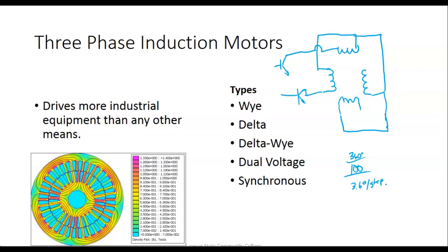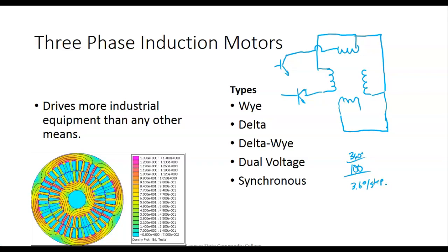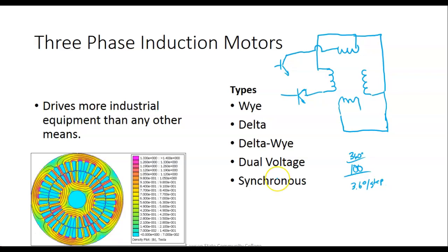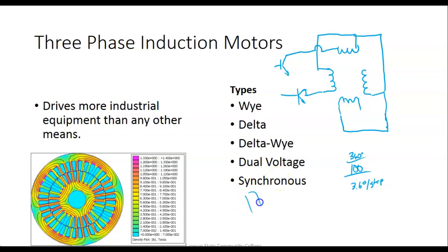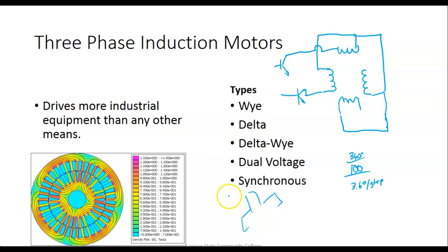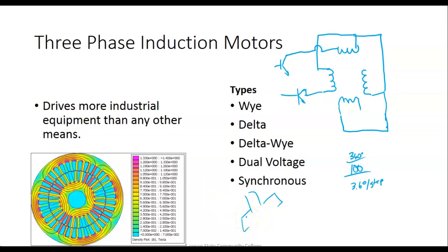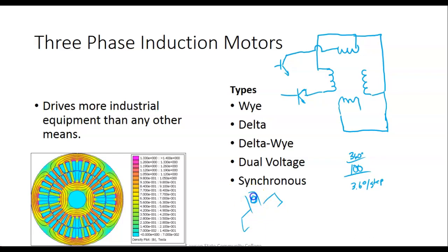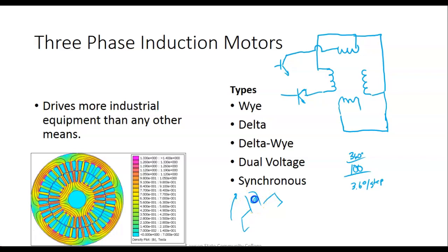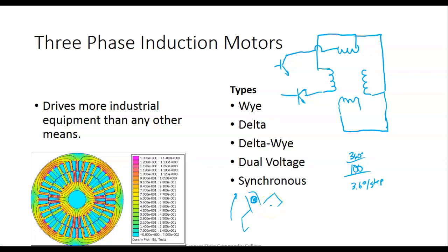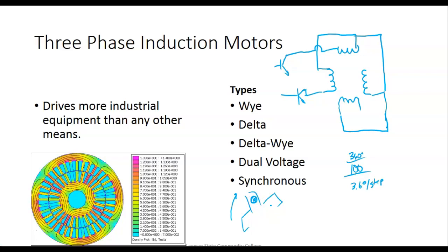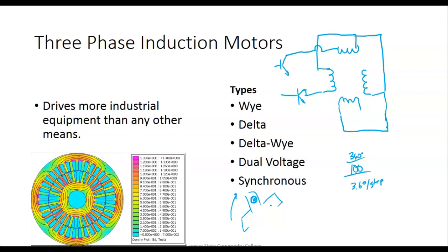Well, I started the carousel running, clicked it off, and got it out in the center. I turned it on, and what it does is it starts stepping, moving real slow. The top is made out of aluminum. I'm not doing a good job drawing this, but under the bottom they've got a metal plate. The stepping motor steps it in the clockwise direction, and it's got holes until the inductive sensor clears that hole. Then it'll step it back so many steps. So I'll show y'all that today. Remind me when we go back to the line, which we might be able to.